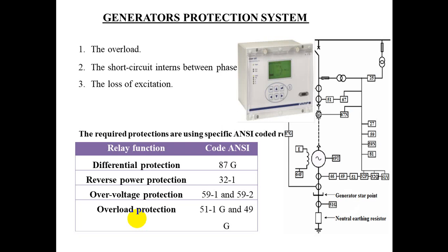It is, however, considered good practice on hydroelectric units, as the response of the governor is comparatively slow and the set is more prone to overspeed. The relay, when fitted, is usually supplied from the permanent magnet generator used for the control of the governor.